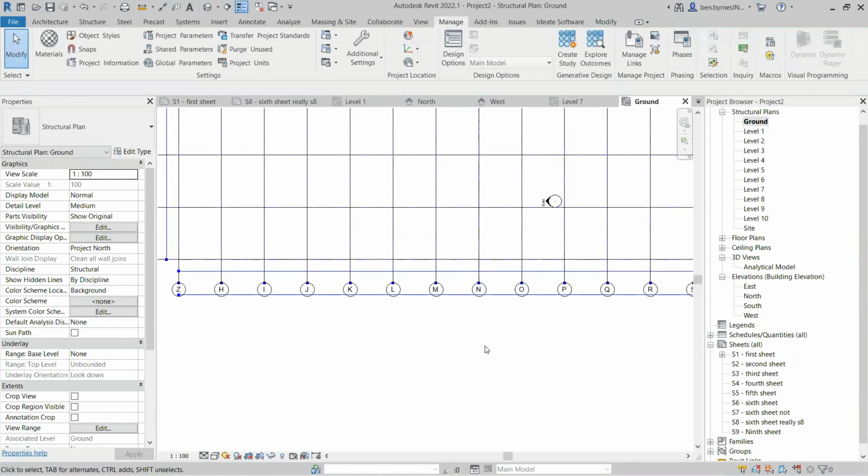But I could bake the previous node to just make sure that it won't overwrite what's in there. Sometimes another workaround for that is you can actually create a group. Just say, for instance, if I needed 2 buildings, 2 grids in there, and I needed to keep the old ones, a good sort of workaround, don't tell everyone, is that you can actually select all the previous stuff that you do want to keep and create a group out of it.